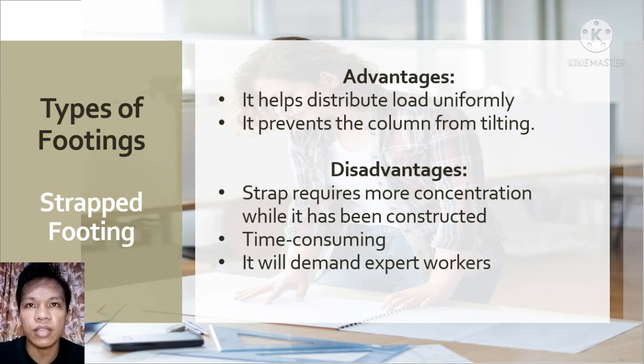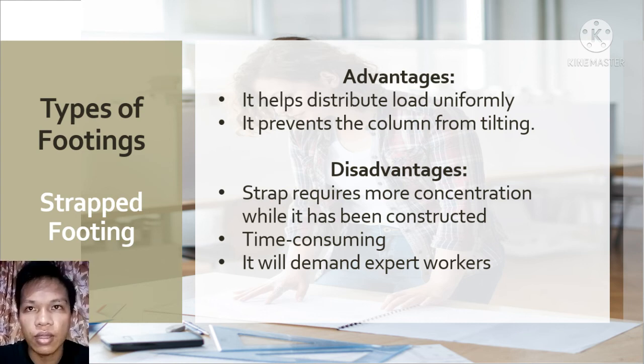Advantages: it helps distribute load uniformly and transfer moment to the adjacent footing. It prevents the column from tilting. Disadvantages: strap footings require more concentration while being constructed because of a difficult design. It can become more time-consuming comparatively, as the calculation of bearing pressure, pressure distribution, moment, forces, and shear can become complex. It will demand expert workers for its construction.